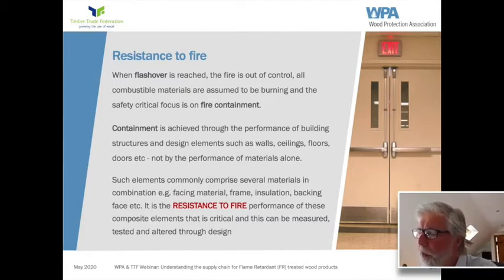Once you get to flashover, all the combustible materials are assumed to be burning. Now, you achieve containment through the performance of the building structures and design elements around the room, such as walls, ceilings, floors, doors. So not by the performance of individual materials or substrates, but by building elements.